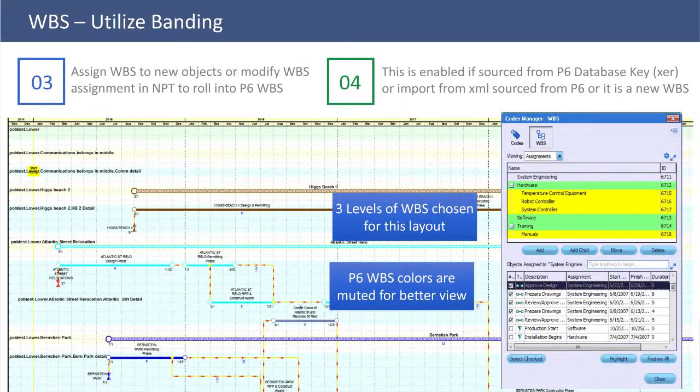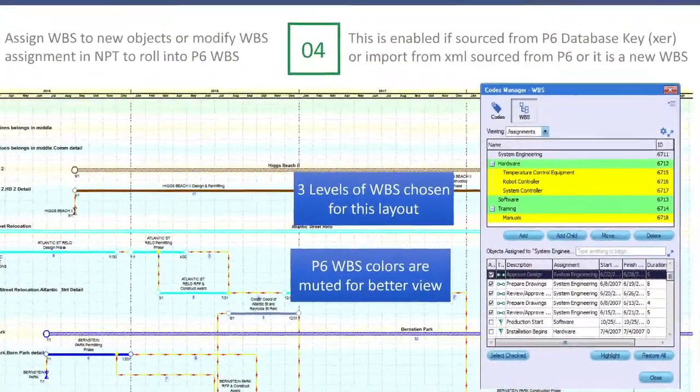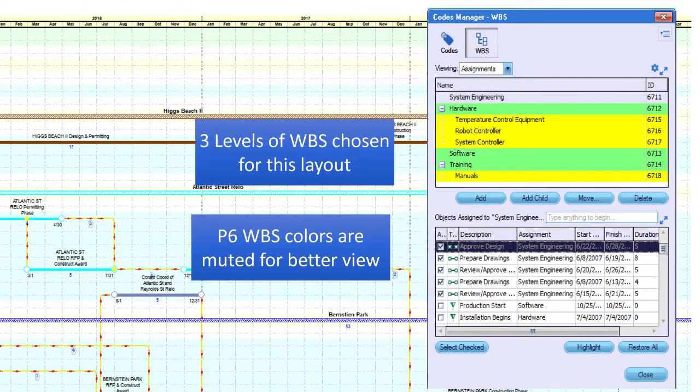So as talked about just recently, incorporation of WBS, which was just this most recent iteration of Netpoint, allows you to use the WBS that you've created in P6 to better organize your Netpoint file. You don't necessarily have to show it using the WBS code structure. You can still go by whatever you want, whatever the feel is of your Netpoint file, but that does exist. And this is the WBS Code Manager, and it works in a similar fashion as activity codes would. You have a list of your activities, and you assign them to whatever your WBS is.